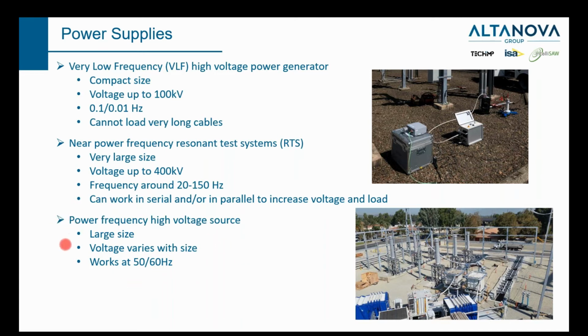The power frequency high voltage power supply works at power frequency, and the size is pretty large. We need to use a truck to load it for the test. And also the size is proportional to the length of the cable, and also proportional to the frequency of the power supply.